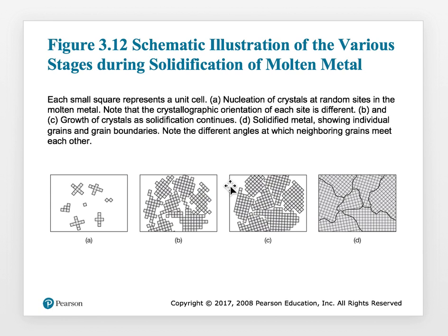Over a period of time, this block is solidifying in one direction, this block is solidifying in another direction, the third block is solidifying in another direction, and so on. So they all are solidifying in different orientations. So over a period of time, this area where there is an imperfect solidification will start creating a line between this block of atoms and this block of atoms. And once this whole block is solidified, then this is a complete line. And this line is not a straight line. It can be a squiggly type of line.